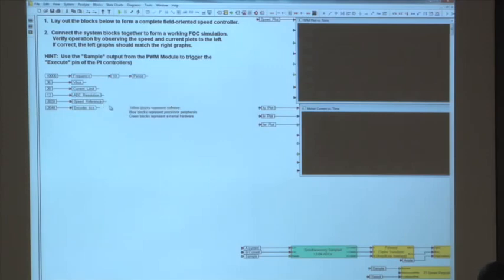So just click and drag over that speed reference variable, Control-C and Control-V, and then run that down to be the input of our reference signal. Okay, at this point, I think everything is connected up.